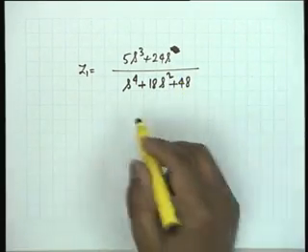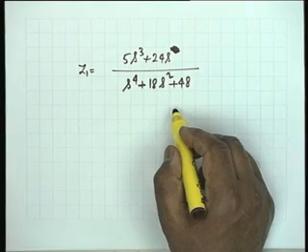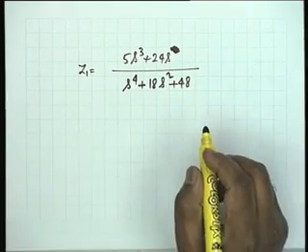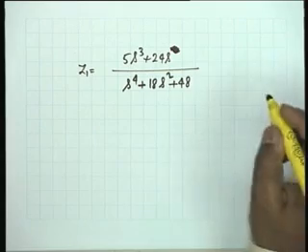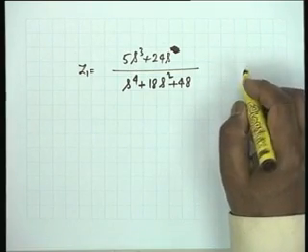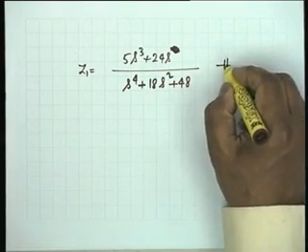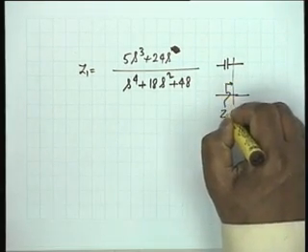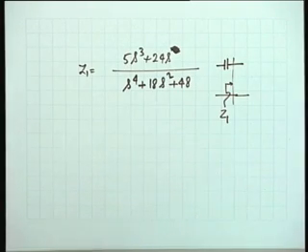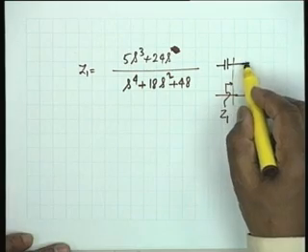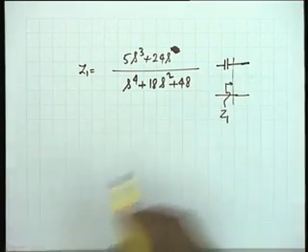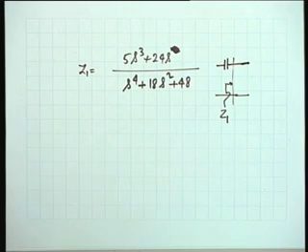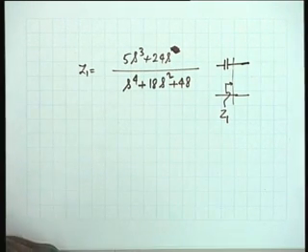Okay. Now, 18 s squared, okay, s squared, because s is cancelled. Now what I have removed therefore is a 1 farad capacitor, and the rest of the function is z1. What we have to remove now is an inductor. I require an inductor. An inductor in shunt represents a pole of the admittance at the origin, and therefore what